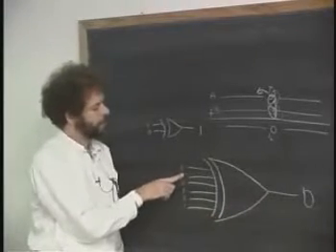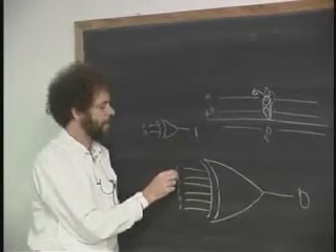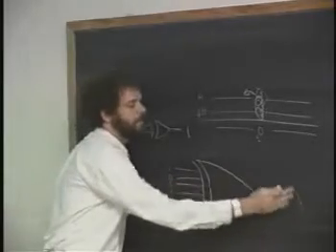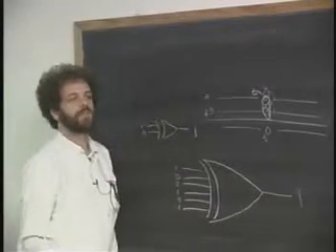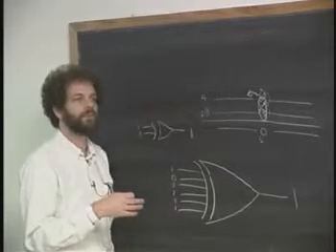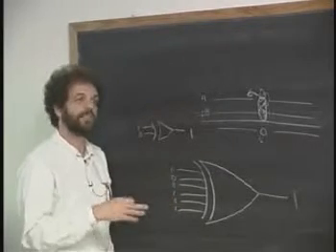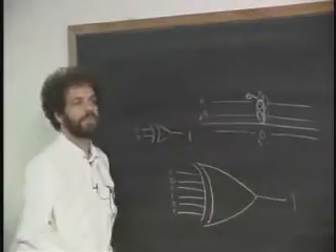And in fact, it has this great characteristic that it is sensitive to a change on any single input with a flipping of the polarity of the output, because it's checking for oddness or evenness, and whenever you add a 1 or subtract a 1, if it was odd, it switches to even. If it was even, it switches to odd, so the output will change from a 1 to a 0.